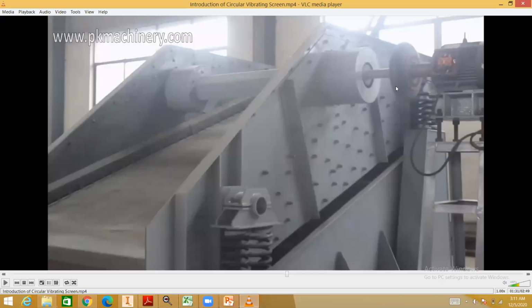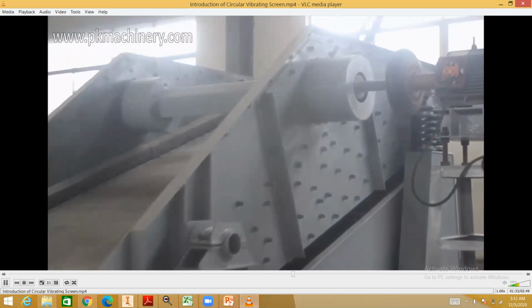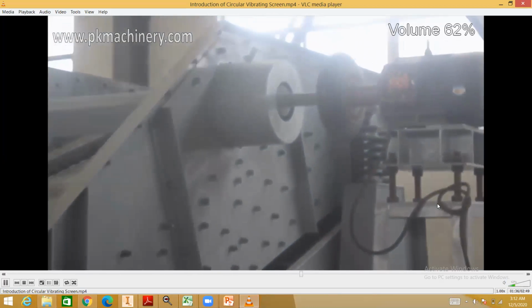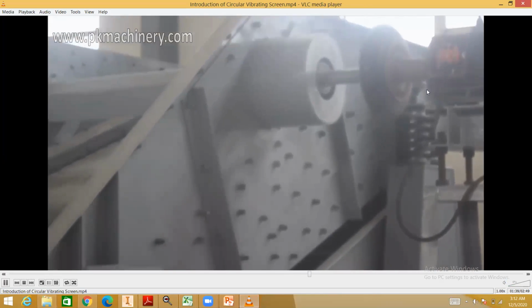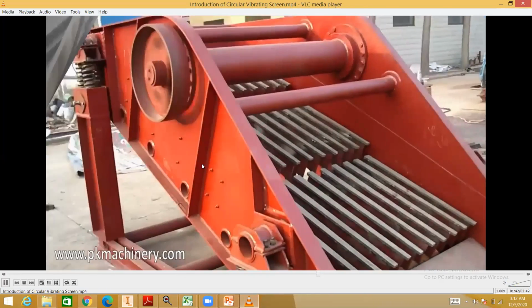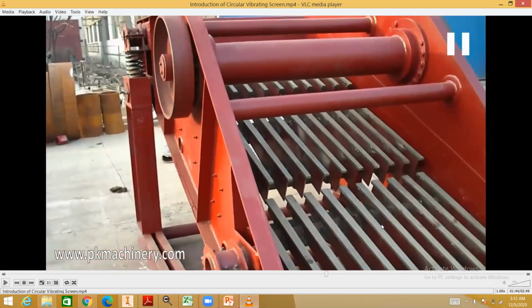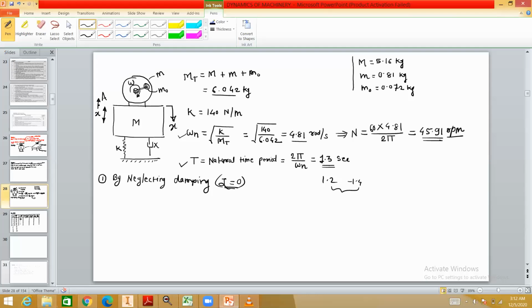And this motor has some eccentric mass, and therefore it will provide an unbalanced centrifugal force. Because of that unbalanced centrifugal force, the system will oscillate, and these oscillations happen because of the spring element present in the system. As we change the RPM of this motor, the amplitude of this platform will change. So we have to find the graph of amplitude versus the frequency of the motor. I hope it is clear what the practical application or the physical setup is, and for such a physical setup, this is the schematic diagram.